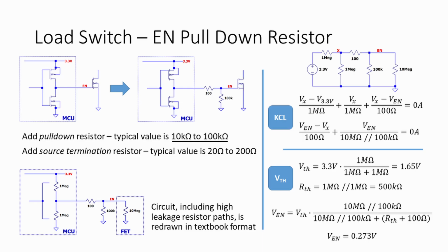You can go for a 10K resistor for a stronger pull-down, but the trade-off is there'll be a little bit more power drawn when the FET is actually turned on. Even with a 10K pull-down, the current is below a milliamp, but that can still matter if you're trying to design something to operate from a coin battery, for example.